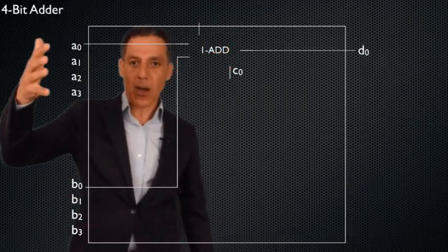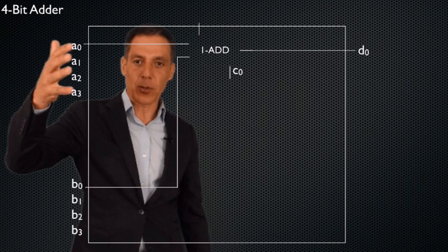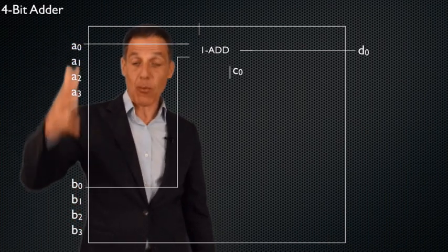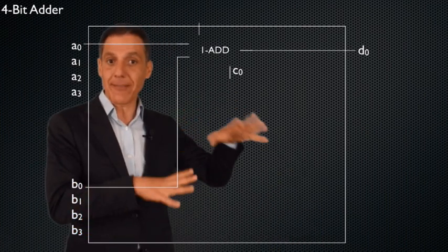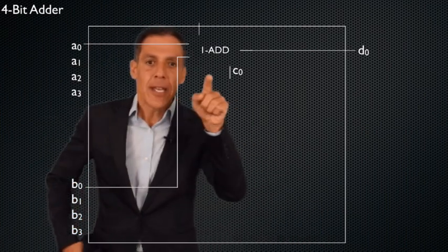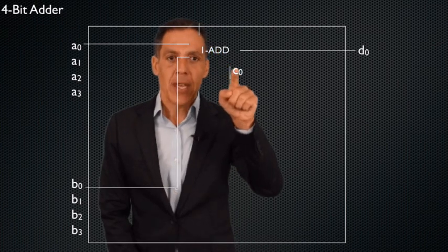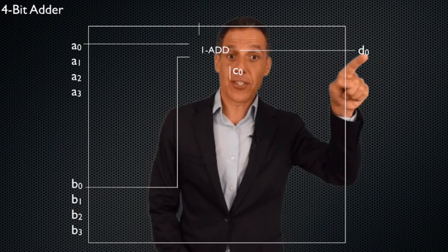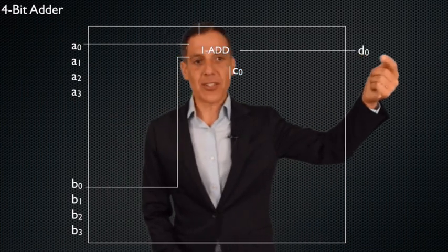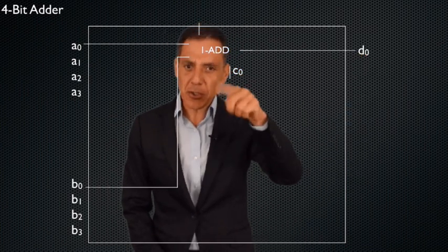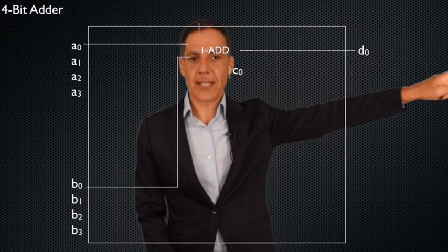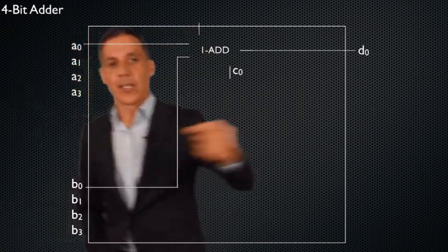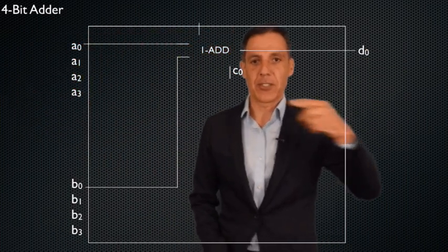All right, so first of all, here are my 4 bits for A and my 4 bits for B. So that's what I want to sum up. I've got those carries I have to bring in. That's fine. We'll do that in a minute. Here's my 1-bit addition right here. Here are my two outputs. There's a carry, and then there's the digit, the sum. Notice, by the way, that this carry is for internal purposes. I don't report that as part of the summation. I just need that to propagate the bits down. So the output outside the circuitry is here.